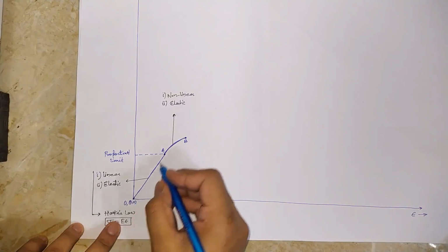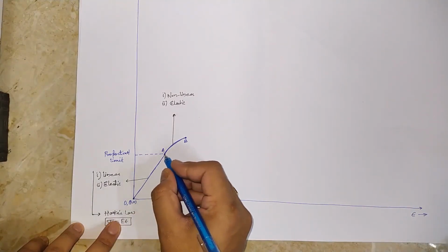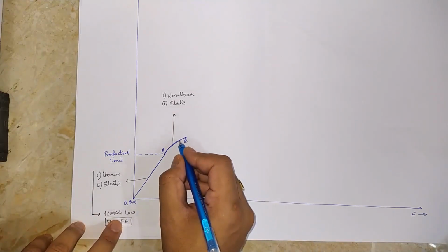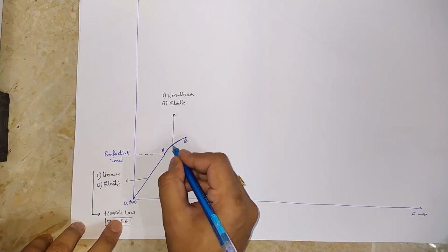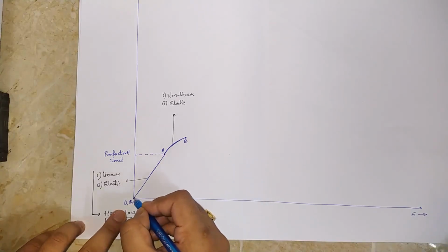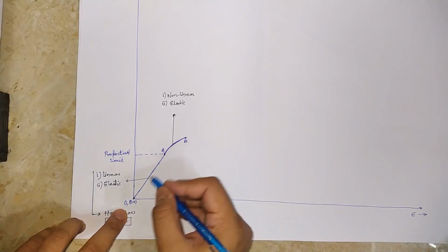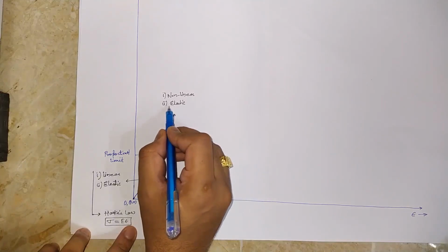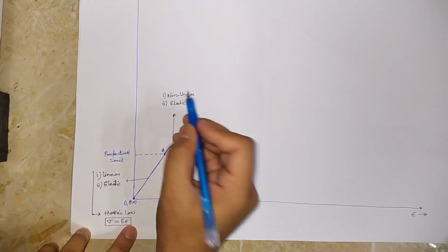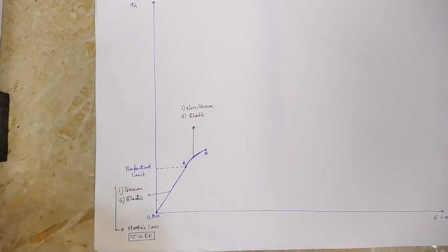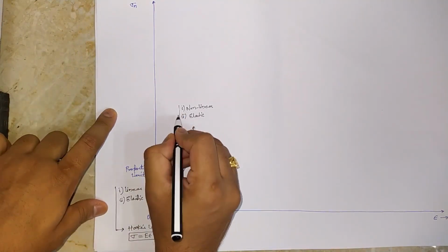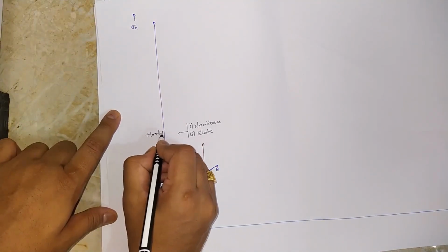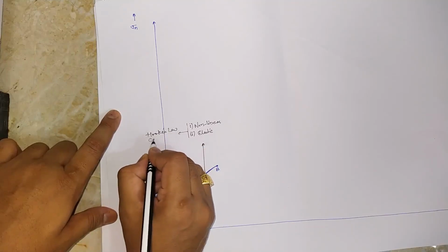When I say elastic, the material's behavior between O to A and A to B stretch of the graph is elastic. Means if at any point between O to B we stop stretching, the material will restore its original dimensions. Okay. But since the material's behavior here is non-linear, Hooke's law cannot be applied.